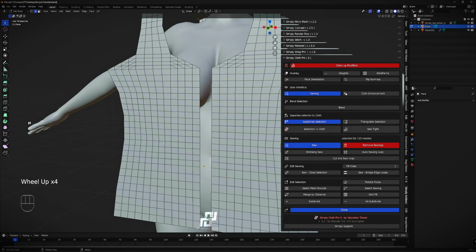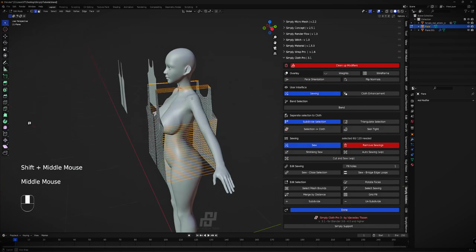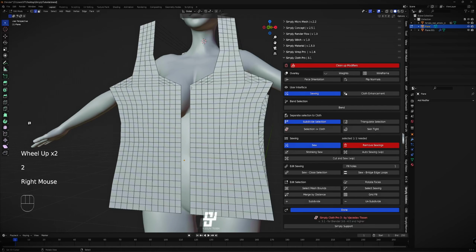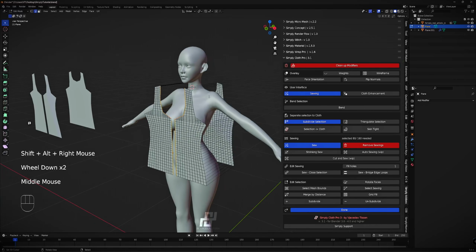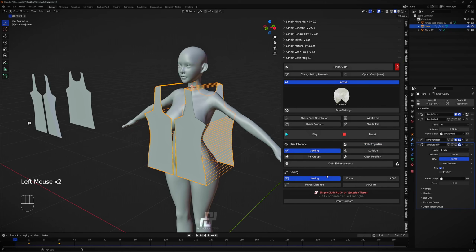What we totally missed is the point about this part here. But don't worry, we will check it now. So I create SimplyCloth, and here we have all the settings. I will go through all of them, but first of all we want the sewings. Checking here, we turn it on. Force we can set up to 5 and check.